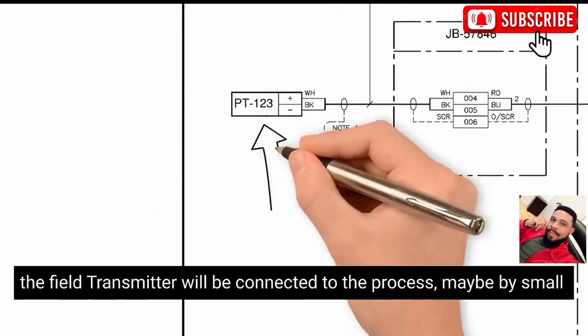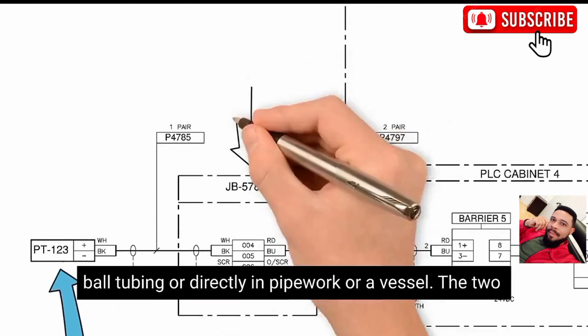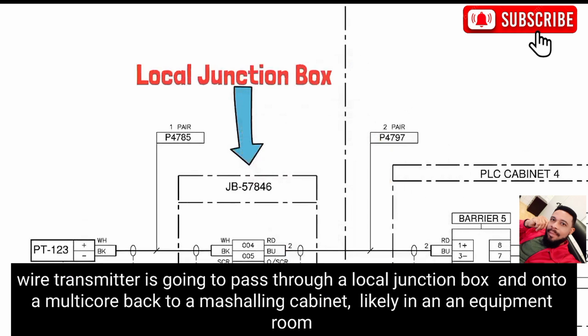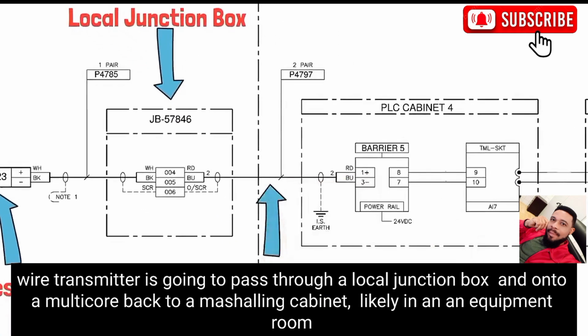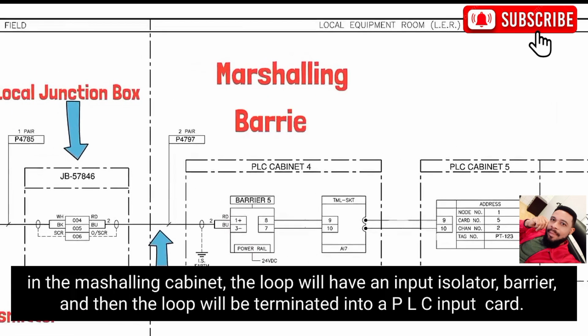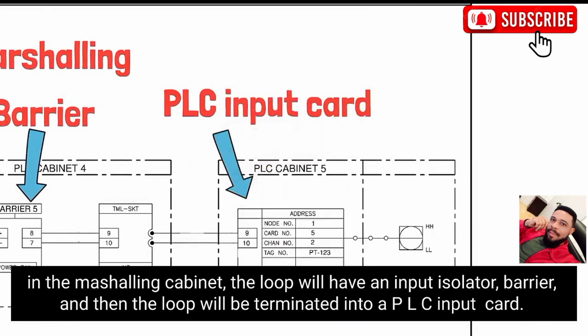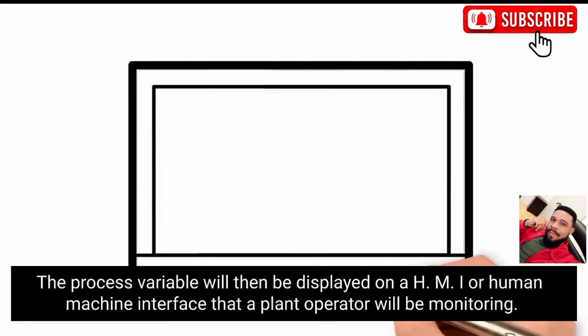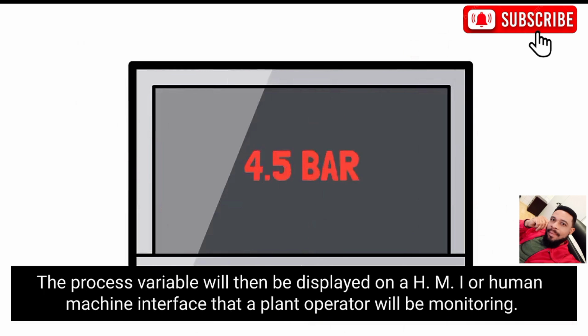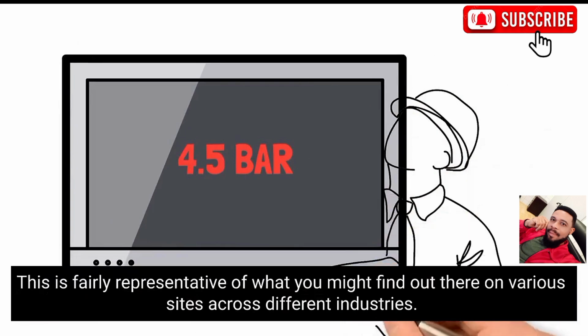The field transmitter will be connected to the process, maybe by a small bore tubing or directly in pipework or a vessel. The two-wire transmitter is going to pass through a local junction box and onto a multi-core back to a marshalling cabinet, likely in an equipment room. In the marshalling cabinet, the loop will have an input isolator barrier and then the loop would be terminated into a PLC input card. The process variable will then be displayed on a HMI, or human machine interface, that a plant operator will be monitoring. This is fairly representative of what you might find out there on various sites across different industries.